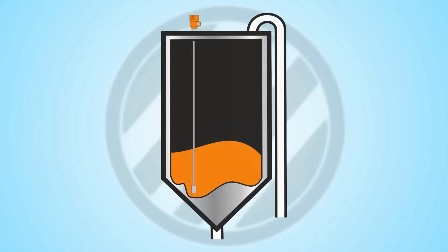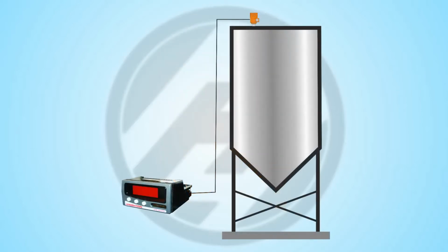In this example, we'll use a standard silo with a total measurement height of 9 meters. For the output we will program 4 mA at 0% and 20 mA at 100% full at 8.5 meters to allow safe headroom. When the signal goes to the display unit, it can be converted to the required information, for example tonnage or any volume measurement. The programming of a Hycontrol digital display is covered in a separate video.